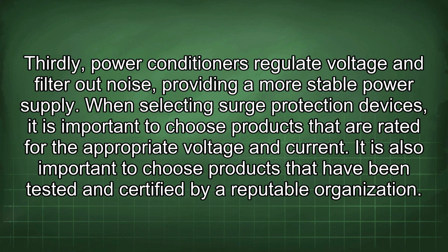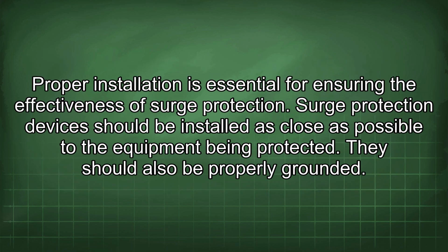It is also important to choose products that have been tested and certified by a reputable organization. Proper installation is essential for ensuring the effectiveness of surge protection. Surge protection devices should be installed as close as possible to the equipment being protected. They should also be properly grounded.